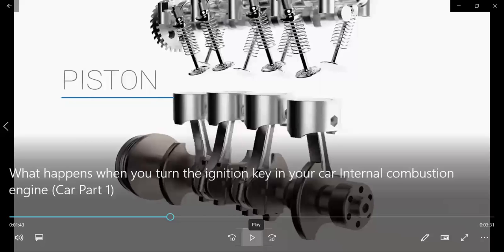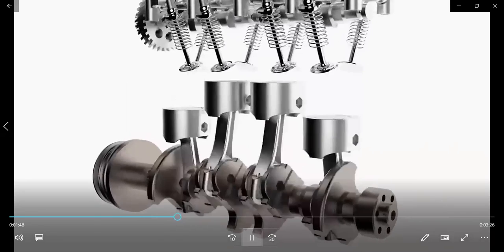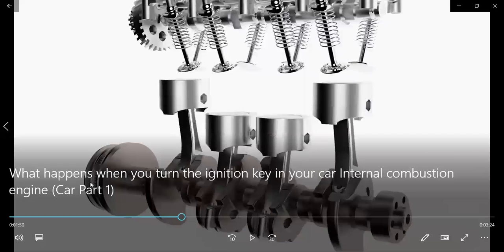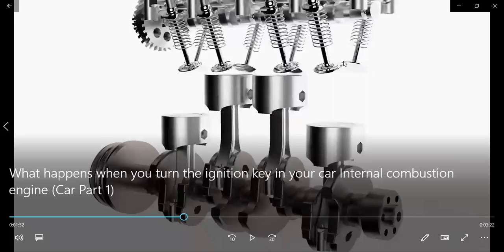The cylinder is basically the space through which the piston travels. The purpose of the piston is to transfer force from expanding gas in the cylinder to the crankshaft via a connecting rod. This is the crankshaft, and these are the pistons which are attached to the crankshaft, and this crankshaft drives the wheels. So the power of this is transferred to the wheels. These are the inlet and outlet valves.